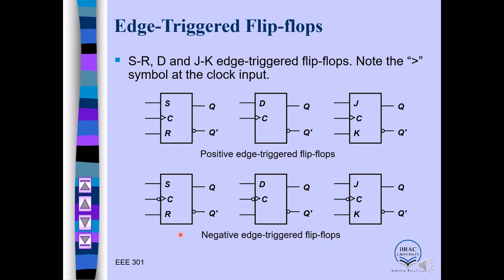And if you look at the bottom part, they are called negative edge, because here there is a bubble on the clock. That's the difference. That means all of these flip-flops work on the negative edge.